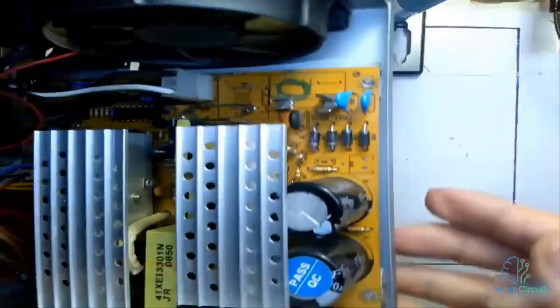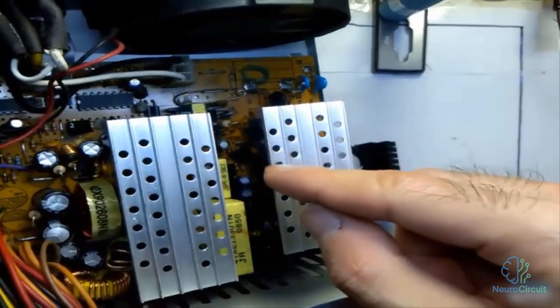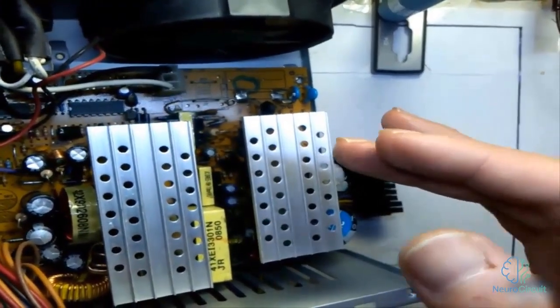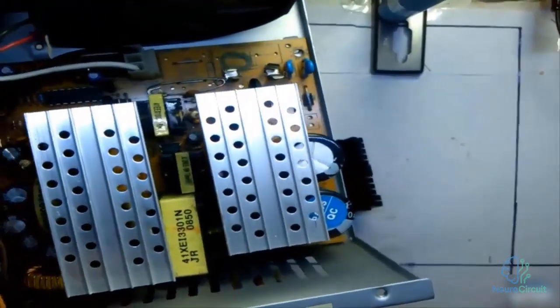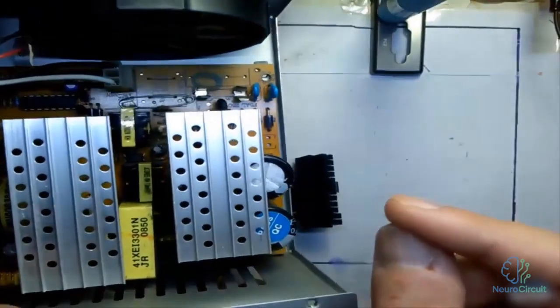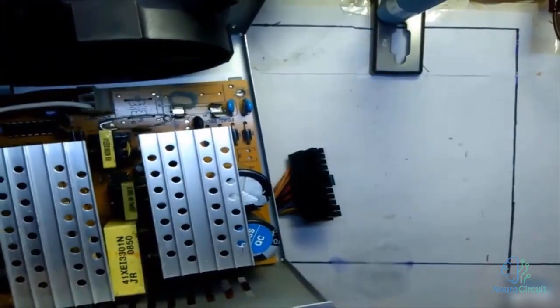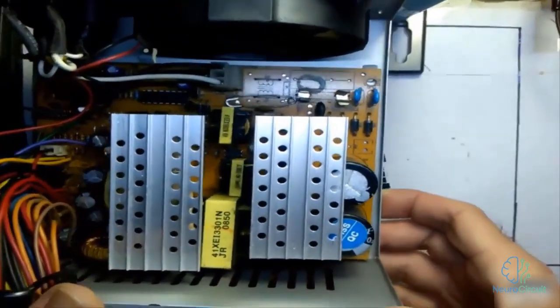What we need to do first is to test the primary circuit. What we want to do is to completely remove the transistors that are here. These are FET type transistors, and let's test its circuit, check the connections of the other components, and be able to repair the power supply. Of course, the repair work. We'll start with a power supply that had an output voltage problem so that we can gradually move towards repairs and it won't be too difficult for you.